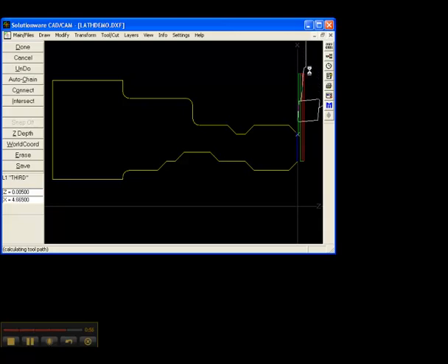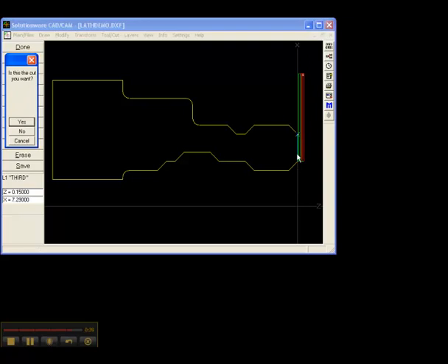Now in this case, we're okay for G-code down to a point. Because the front face of the part has this big open bore, it didn't know that you wanted to go all the way down to 0, 0. It kind of went down to where the highlight ended here. So we're going to kind of stretch this cut out a little bit more to include this bottom area, so it goes all the way down to Z0, X0, even though this ultimately will be bored out later.